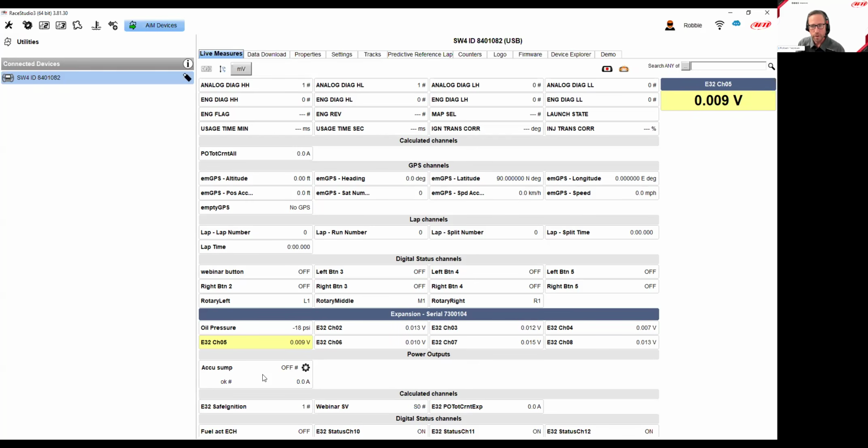It has a current, how much current it's actually distributing to everything, and then whether or not that power output is healthy, whether it's short circuit, open circuit. So finding that information was somewhat cumbersome because it was a lot. Now we have 64 data channels just in the power distribution, not including the analog channels or the ECU.